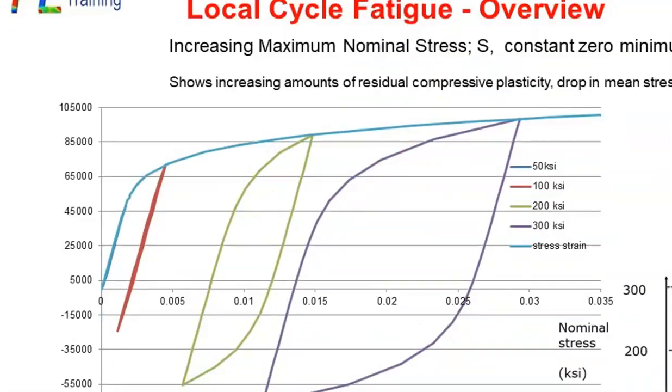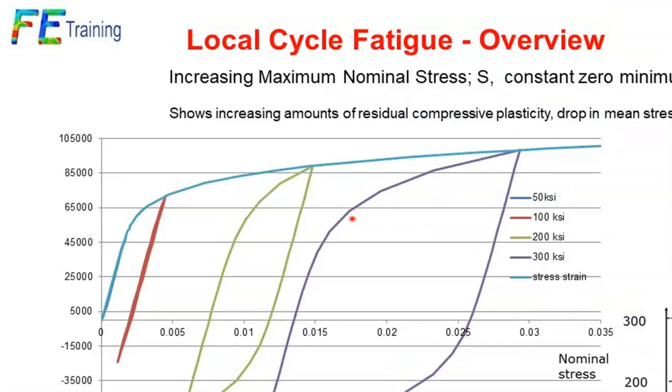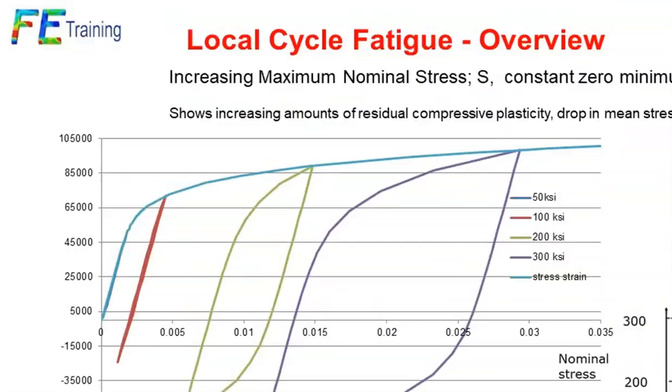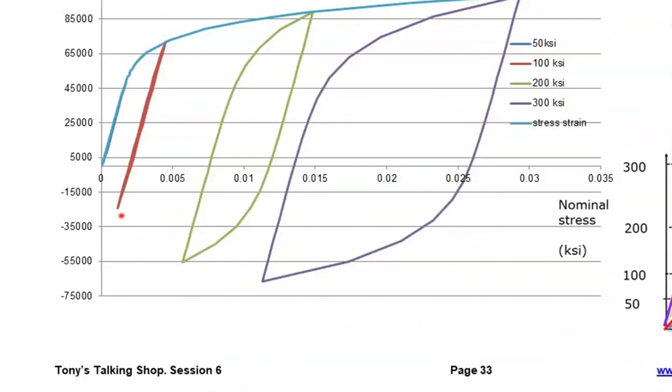This is basically a whole series of results. In here we've got our fundamental nonlinear stress-strain curve. We could get away with high cycle there, and there. There's not much evidence of plasticity going on. As we get to this level of loading, we've got more plasticity coming in.